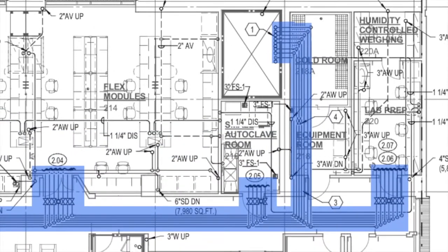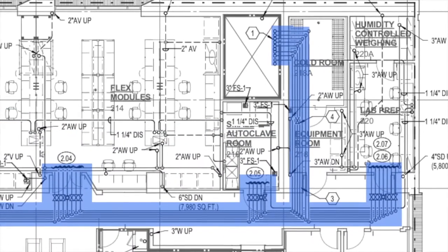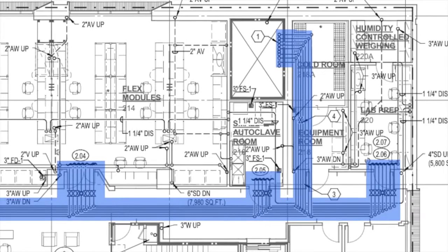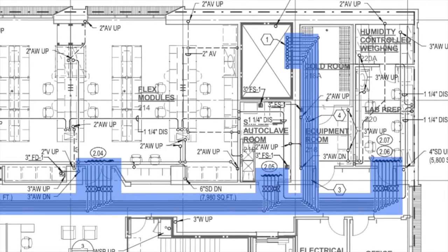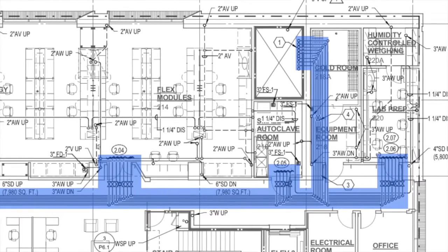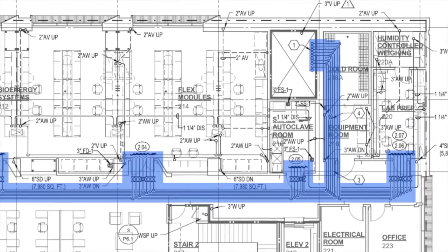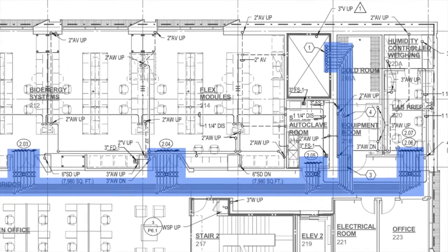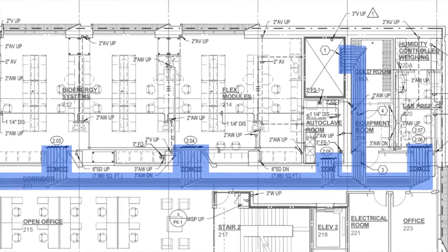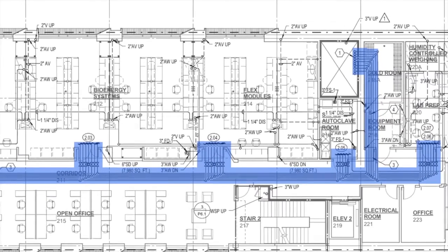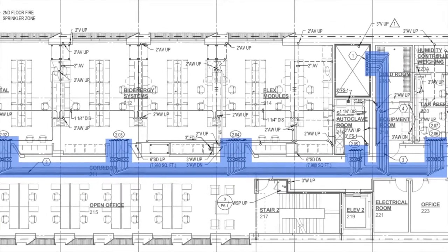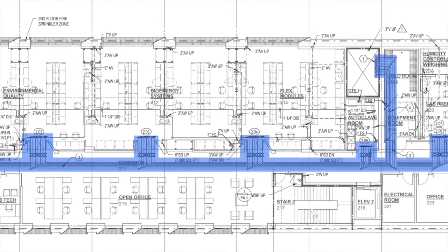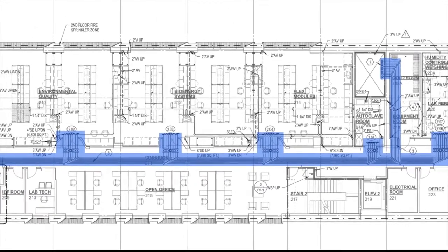On the second floor, the same strategies have been implemented. The mechanical room marked with the large X is where the plumbing lines start. From there, cold water, hot water, waste, and ventilation are run to each room. On the first floor, there are 6 outlets running from the mechanical room. The pipes to each room have been categorized as 2 cold water, 2 hot water, 1 ventilation, and 1 wastewater.